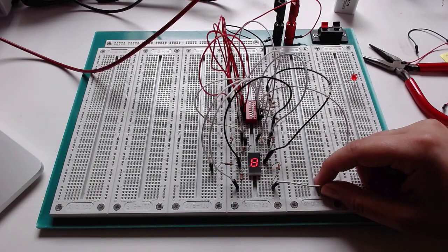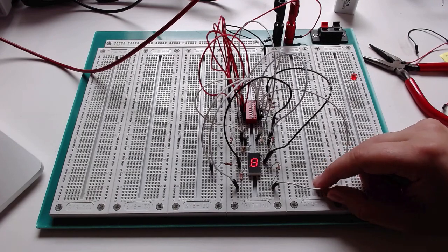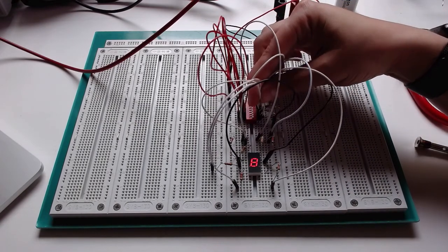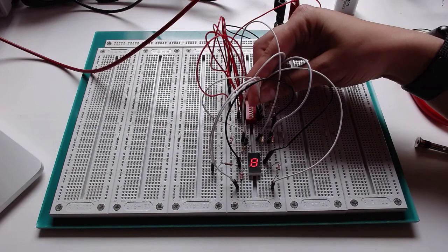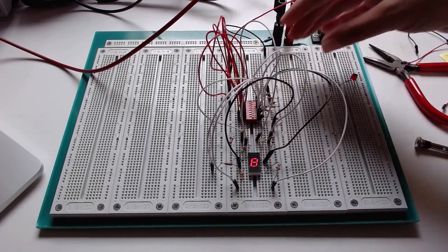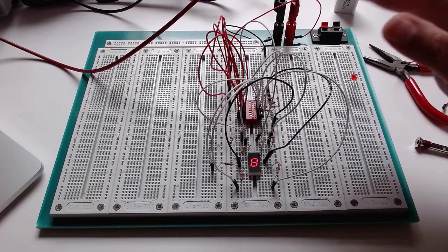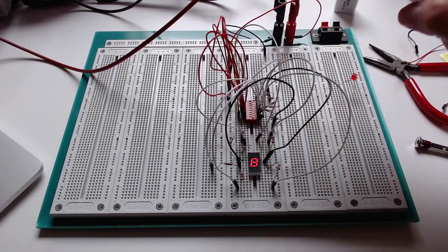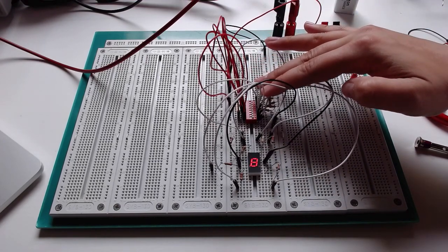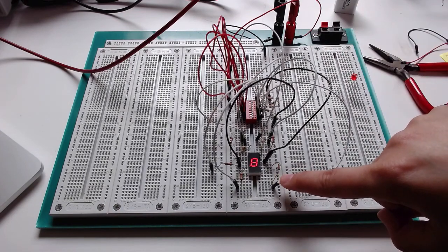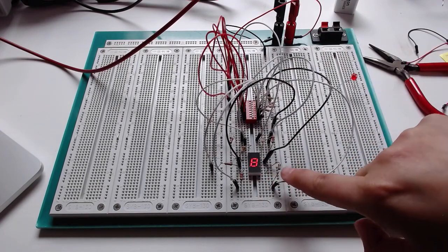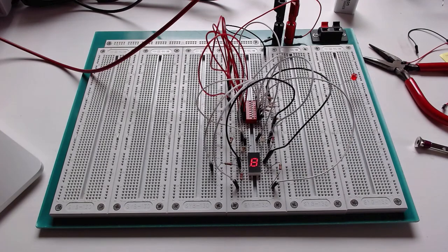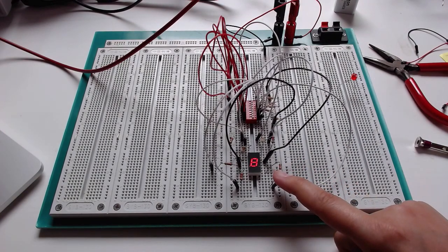Okay, so I know it seems a little bit weird, but this is how a 7-segment display needs to be connected. Now I have this connected to a dip switch, but these 7 wires could just as easily be coming from I/O pins on a microcontroller or from the output pins of a 7-segment decoder. Whether these signals are coming from a logic chip or from a microcontroller or from a dip switch, it doesn't matter. We still need to have every single one of these connections to the LED anode go through a current limiting resistor.